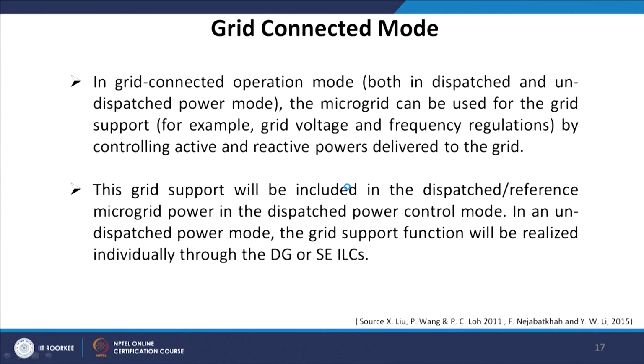Very important. This grid support will be included in the dispatched reference microgrid power in the dispatched power control mode. In an undispatched power mode, the grid support function will be realized individually through the distributed generators or storage elements or interlinked converters.